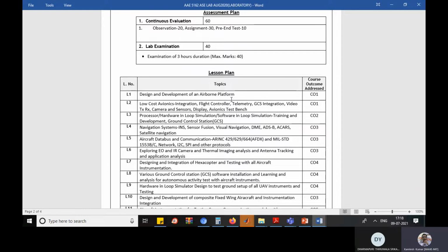Okay, so you should have a skin on top, and at the bottom some material which makes it hard. So that is the mold. A mold can be made of PU foam. You have to machine it using a CNC machine, like 3D machining. There will be a CNC engraver machine which will machine the parts as per your 3D designs.